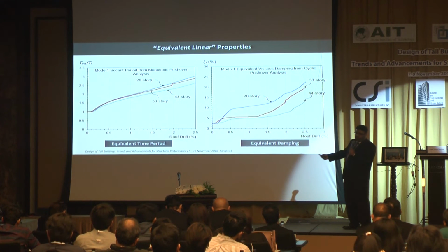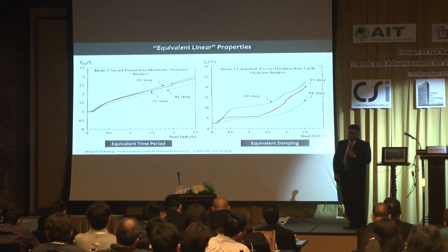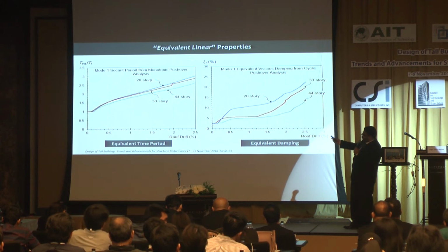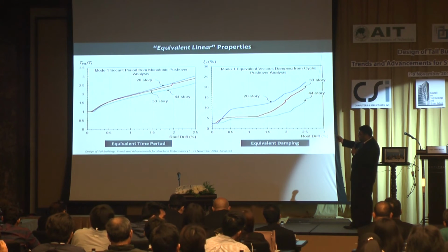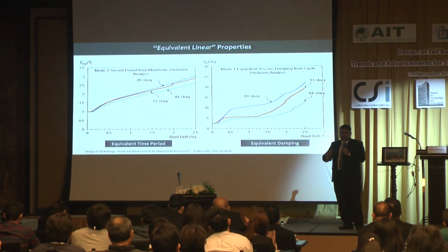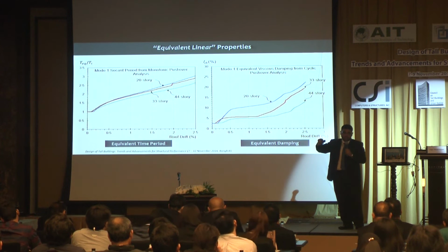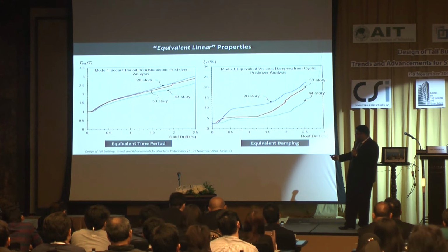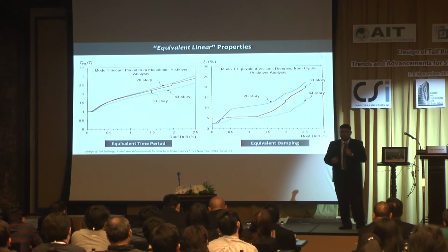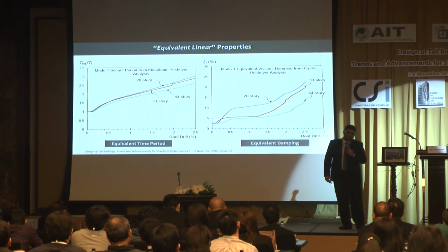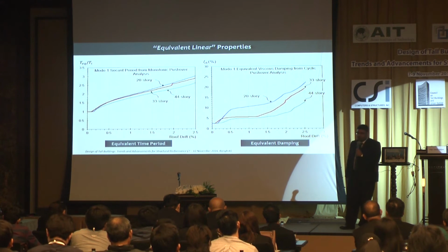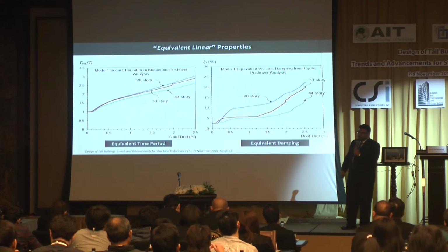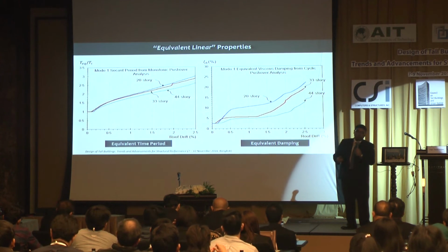We did this procedure, by the way, for 3 case study buildings as I showed before, and these were the results we got for the 20-story, the 44, and the 30. The trend shows that we may come up with a general curve for period elongation, and this is our ultimate target. We want to present this modified response spectrum analysis as an improved design procedure and not as an improved performance-based analysis procedure, because it is still a linear static procedure based on modal superposition. So it has all those limitations.